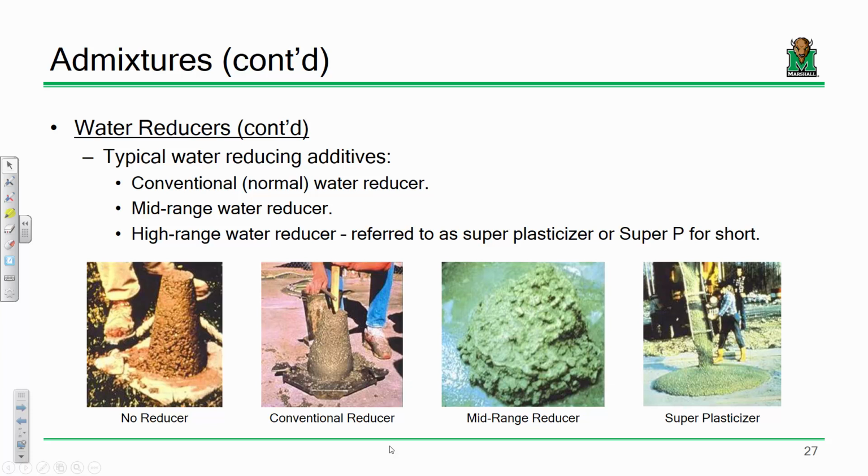For those of you that don't know how a slump test is performed, it's pretty basic. There's a flat surface and there's a very standardized metal cone that you set on that surface. You fill it with concrete in various lifts, rod 25 times. You all have already had experience with rodding samples because we did that with the mortar cubes. Rod it so many times, level it off, and then when you lift it, you don't twist, you lift straight up, okay? And lift it at a somewhat controlled rate.